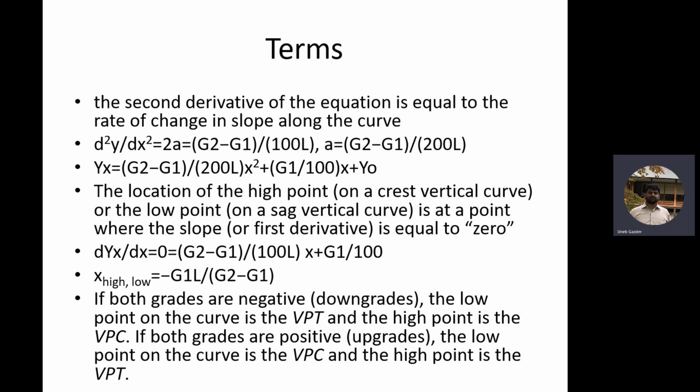Doctor, in calculating the elevations of PI and PT, do we consider the sign for the gradient? We did, right? Plus 4. When you were calculating VPT, we did minus 2. Was the minus because it's lower or because of the sign? Because of the sign. When calculating elevation, the gradient is downward, so you are supposed to subtract it, right? You want a lesser value. Did I get 1243? I don't know. Maybe. You calculated it. If you don't know, how can I know?